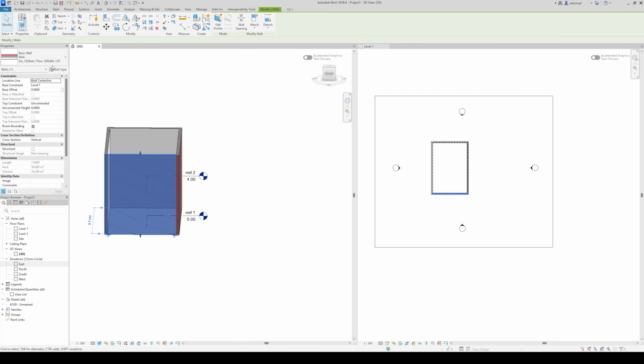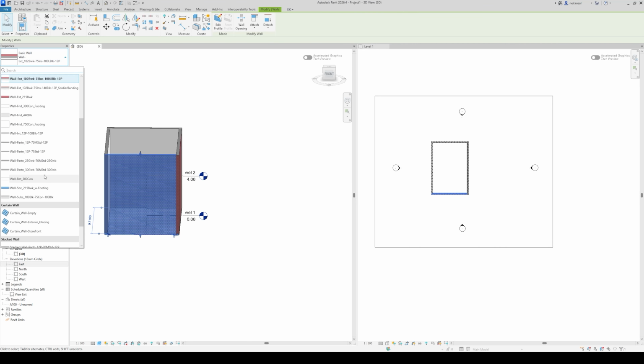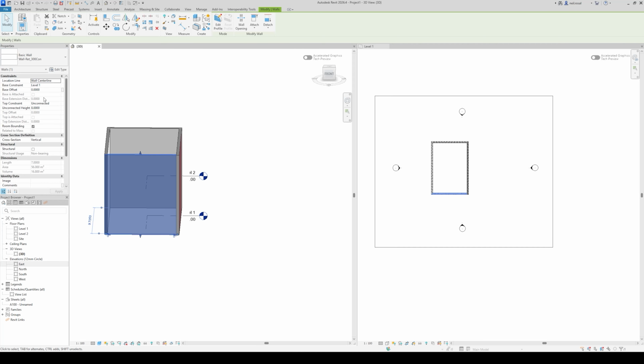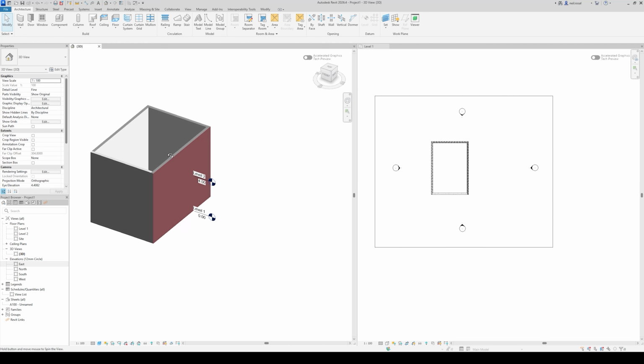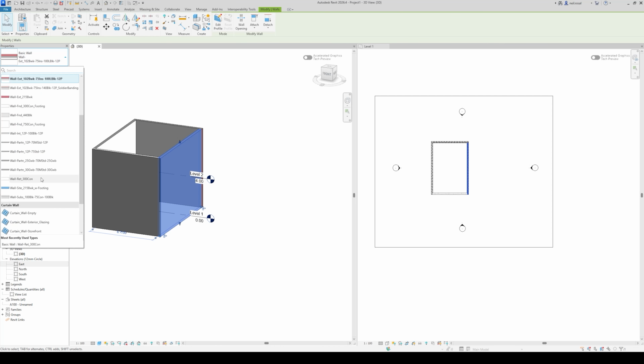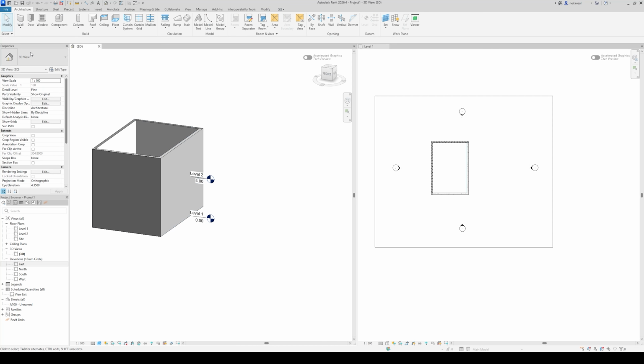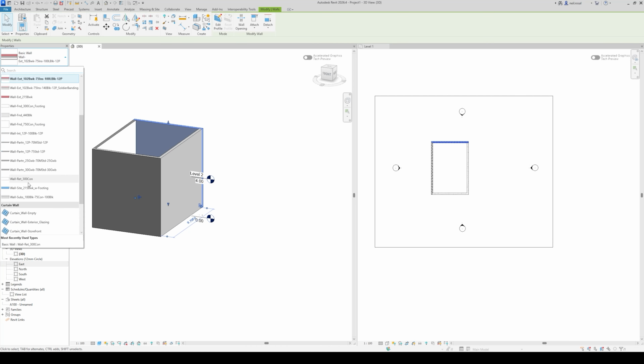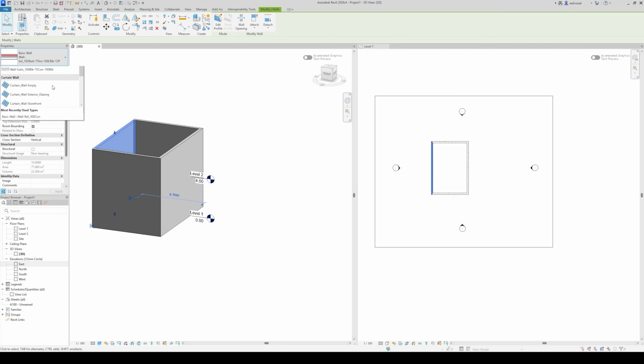You can select what wall type you want. Over here, as mentioned earlier, we have these things called templates. Templates provide different types of walling because walls are considered families in some cases. So I can change my thickness to maybe a 300 millimeter concrete wall. I'll go with that, changing this. And you can also create your own thickness of walls in Revit.